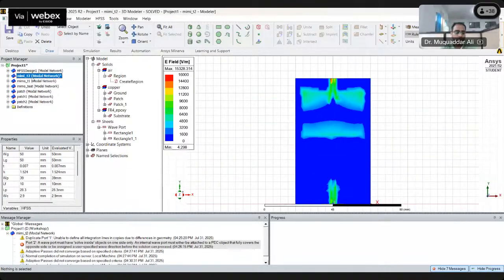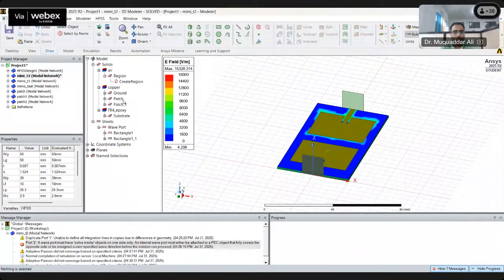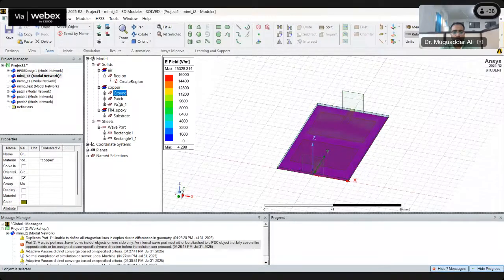In these two, what we are doing, we are simply moving the position of our antennas. So that is known as spatial diversity. Spatial diversity, that means we are changing the position of antenna. We are keeping them far apart so that they do not couple with each other. So for this, we need at least lambda by 2 times the distance.